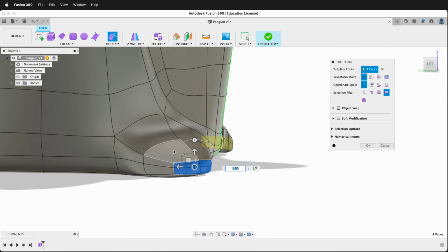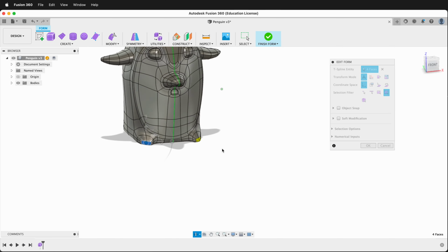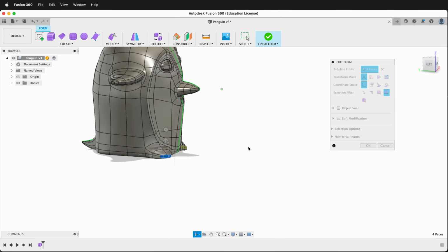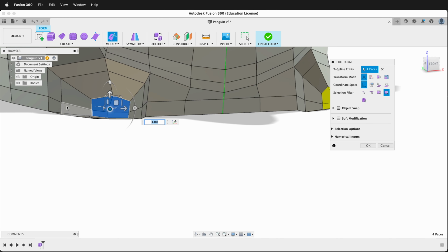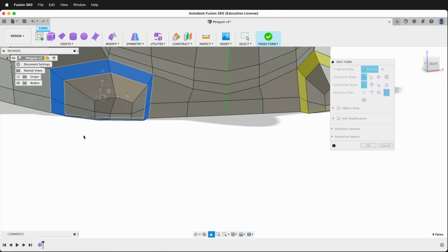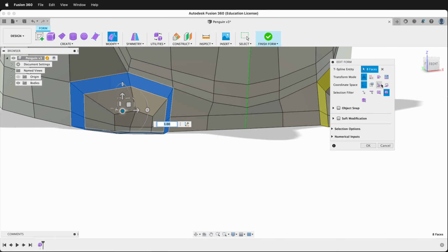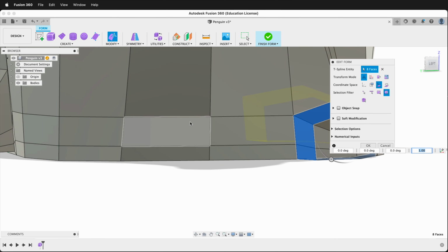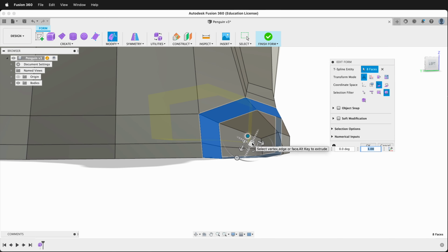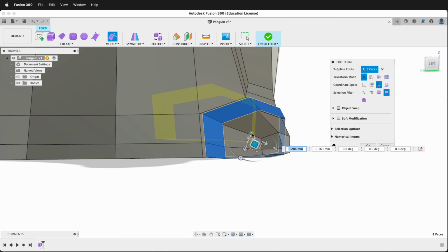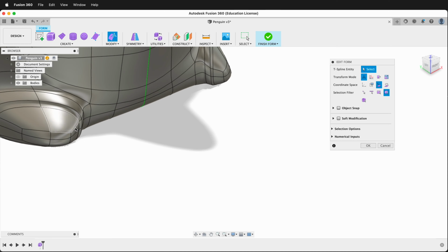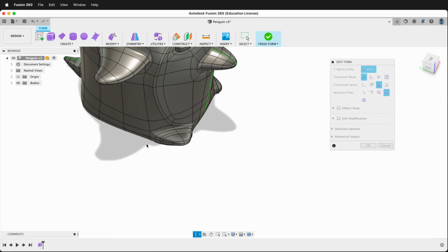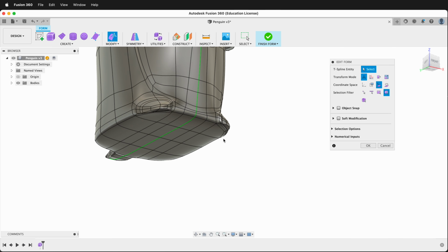That's looking good, but I think we need a little separation between the feet and the fur because they're definitely different color. So I will go back to box mode and let's go ahead and click this ring. We can shift and then double click, and then we can just extrude it out by going selection space. And then if we just hold Option, that'll pull that out there. And then we'll just scale that down just a little bit. And then let's see what that looks like in smooth mode. Yeah, so that gave us a little bit more separation there. And I think those are pretty good little nubby penguin feet.